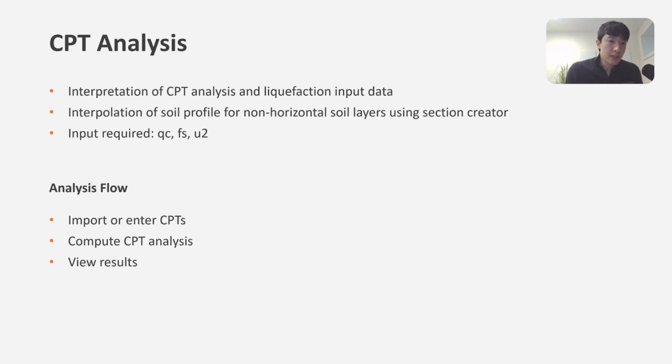Settle3 has the CPT analysis, which is the interpretation of the CPT data, and that can also be used as liquefaction input data. We have interpolation that can be used. The CPT data can also be used to create the soil profile for non-horizontal soil layers with our feature called Section Creator. I'll explain that in more detail. As long as the user provides the CPT with the qc, fs, and u2 parameters, they can do the CPT analysis in Settle3.